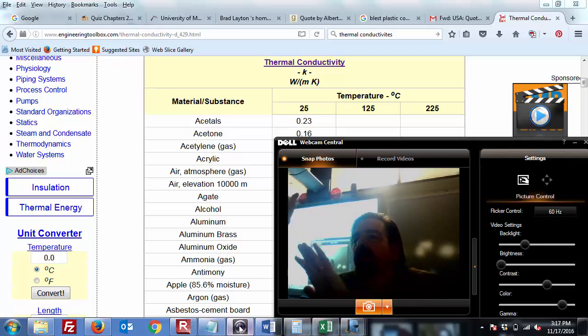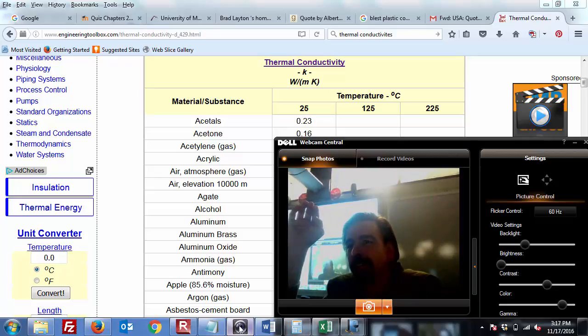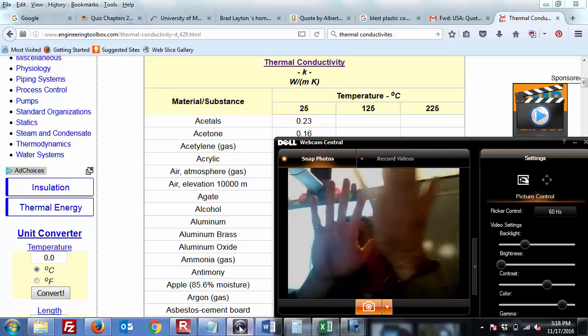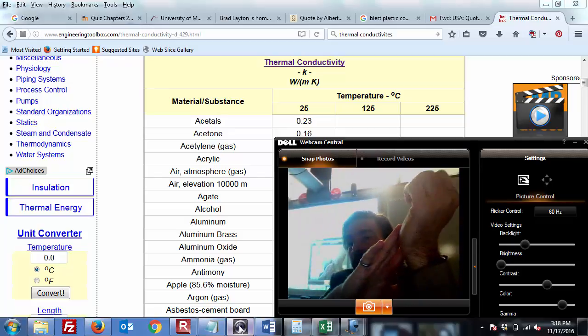He touched the two and said, "Oh, look, you can tell that this is fake rock because the real rock is colder." Well, all of the materials in the room are the same temperature. The air is 70 degrees, the walls are 70 degrees. But the reason the natural rock feels colder is because the thermal conductivity is greater.